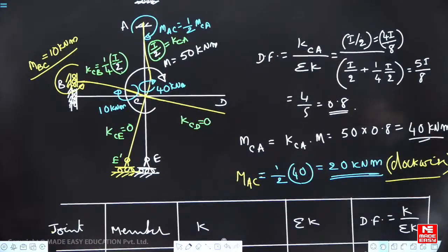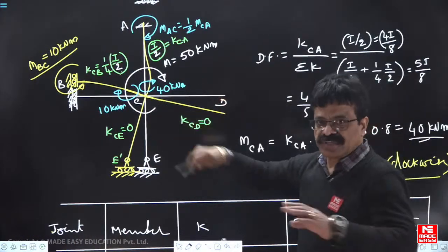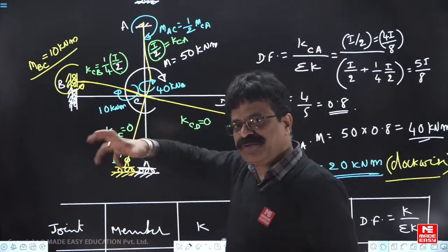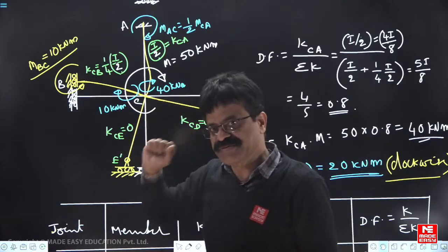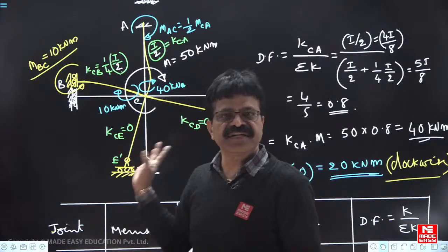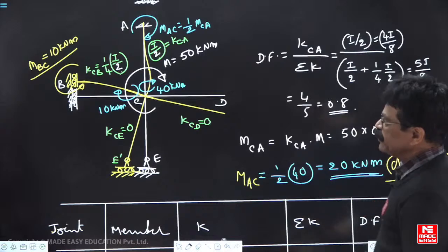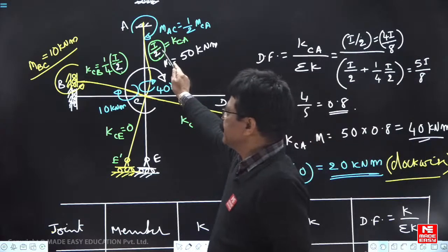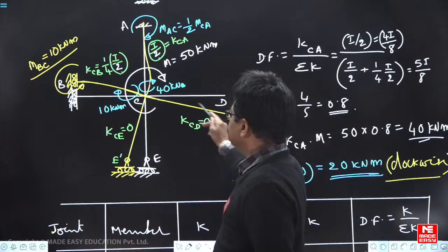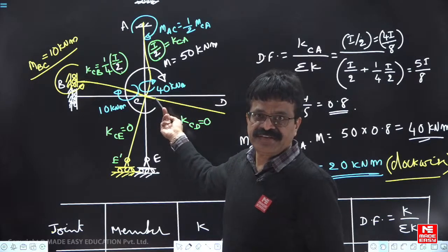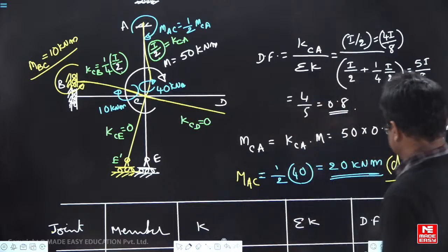Right? If you are able to draw the deflection profile after applying the moment, that will decide what should be the relative stiffnesses of each member, and accordingly proceed. We have given you the list. This is 3EI by L, this is 1 by 4 EI by L. If we have a hinge support here, we will write 3 by 4 EI by L, like that. Fine.